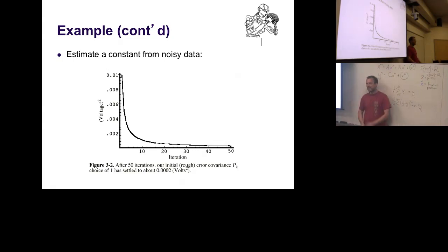In nonlinear systems, this is not true, and everything can become very complicated. If you do state estimation with filtering, it will actually affect what you can control afterwards in a strange way. You get interaction between both processes, and things can go arbitrarily wrong. So people are very unhappy about this in nonlinear systems. But in linear systems, it's great. Filtering and control are two separate topics. They simply separate automatically. Just nice to know.